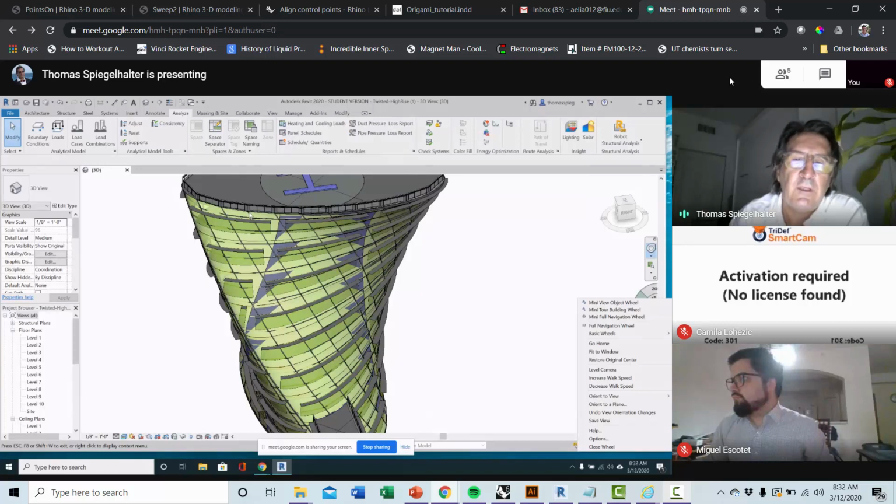And we even have a facade family that is already in place on the conceptual mesh, but Revit automatically brings it down to 40%, and it adds automatically a shading system. Now you can replace that shading system with any manufacturer Revit family file, whatever you find on the market and you love it, and the client as well, with this one.